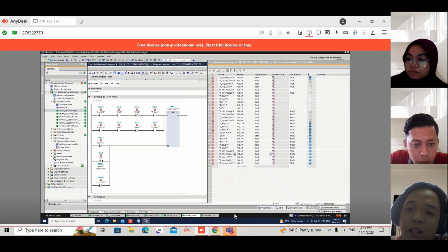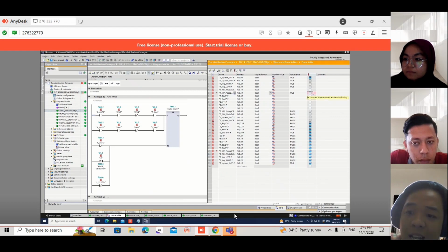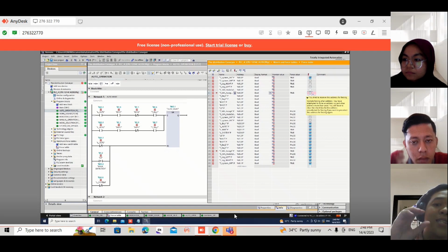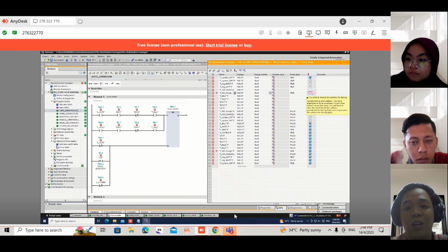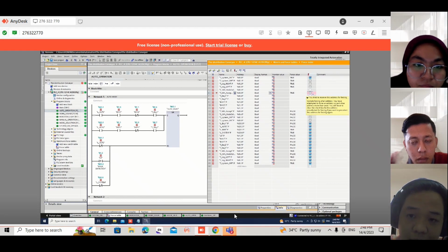The conveyor belt will start moving to the right when the proximity sensor in bay 1 senses that something is there, like a part, and the proximity sensor in bay 2 senses that nothing is there, it is not occupied, and someone presses a button called bay 1 momentary contact.